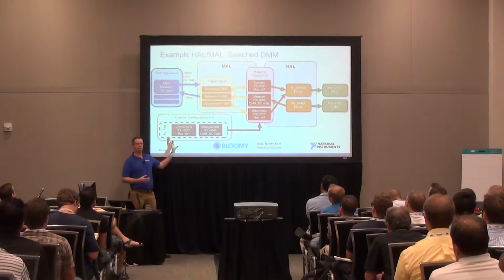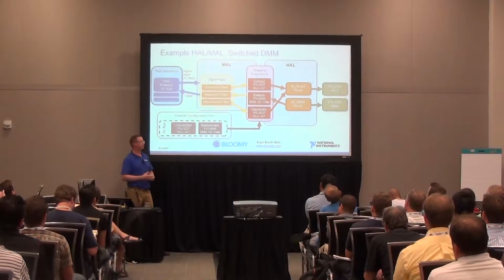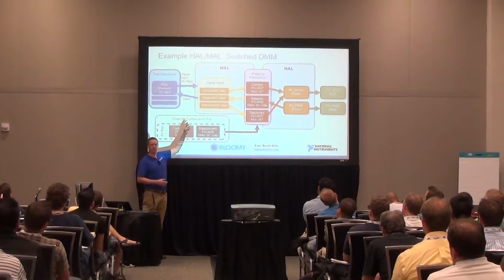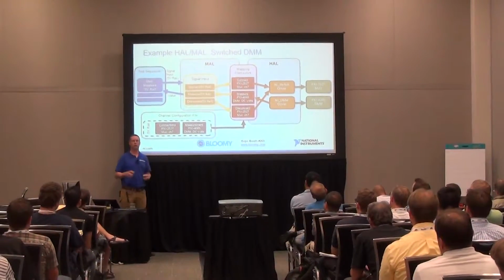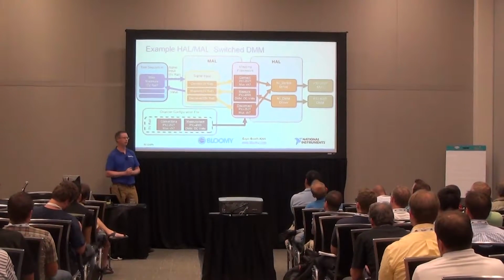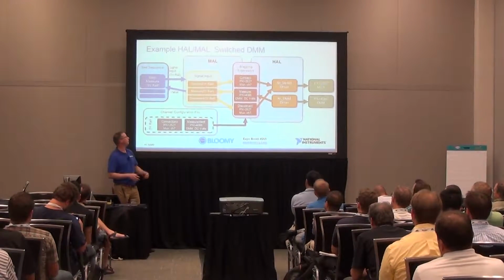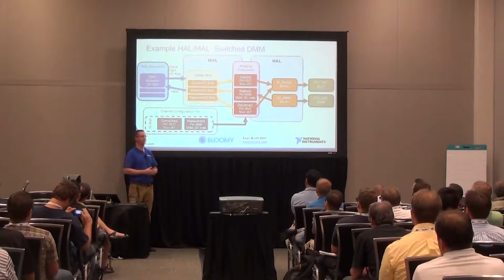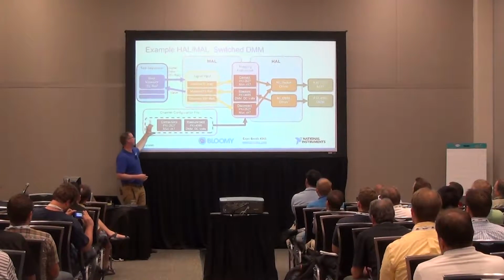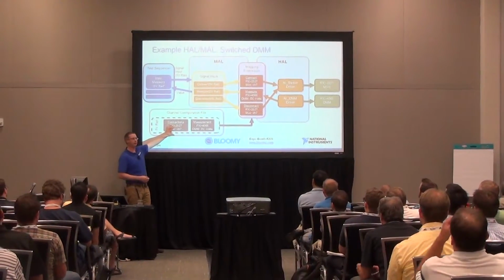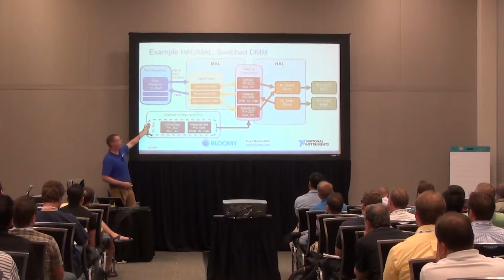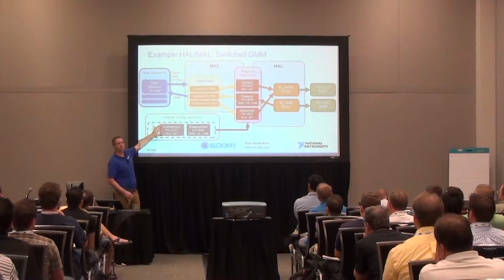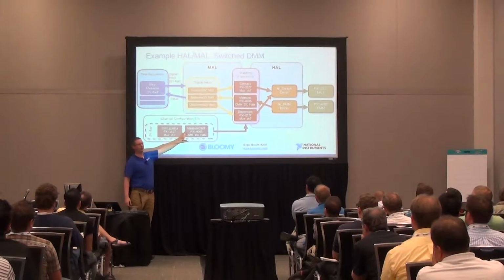And our signal input is kind of like creating a recipe. It's saying, I need to connect something, I need to take some measurement, and I need to disconnect something, all using this 5-volt rail signal name. So it passes that information down to your mapping framework. The mapping framework aggregates that with your configuration file. And the configuration file has an entry for 5-volt rail, which says I have a connection associated with 5-volt rail and I have some measurement device.